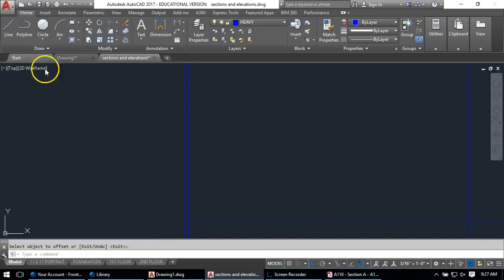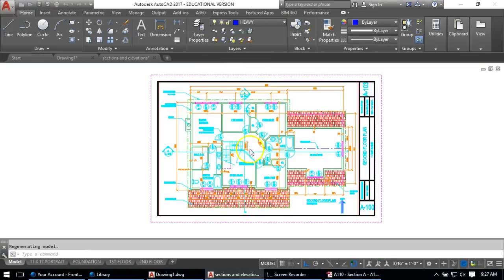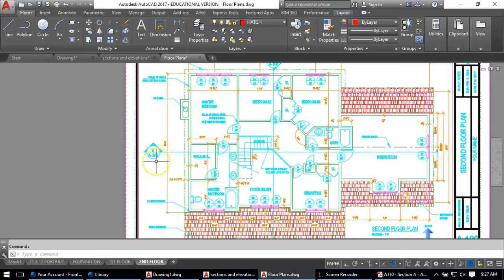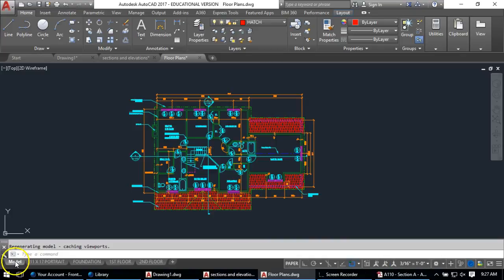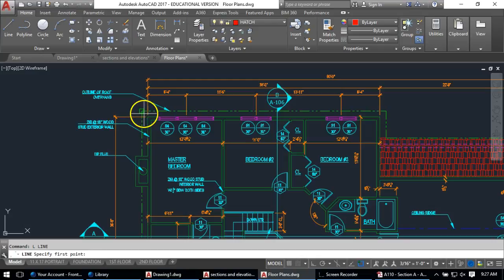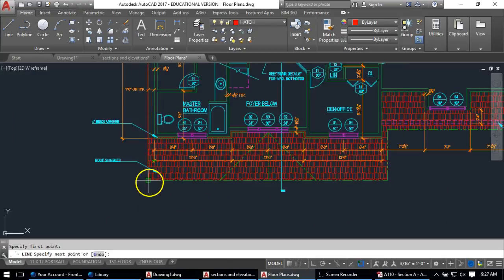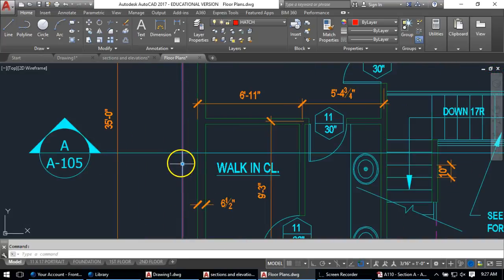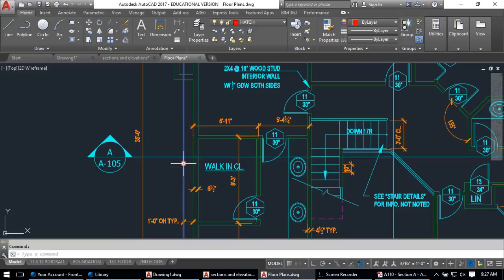Let me open up the floor plan here again for a second. Maybe this was a difference again. I don't know where they set the section cut, and now my section cut is set. This might have been the key. My section cut is not halfway through the roof. If I select my roof plan, or if I draw a line from the top of my roof all the way down and select this, we can see the halfway point is here. That's going to be the peak, the highest point of my roof. All right, but my section cut is up from it by a little bit.